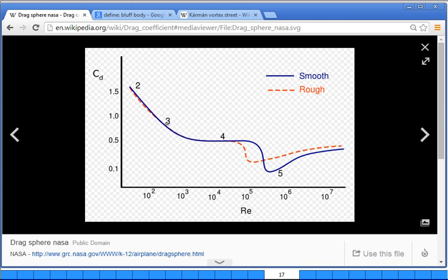But then what happens is you still have laminar flow over it, but it's difficult to recover the pressure to come around the backside. Something happens on the backside. It starts shedding vortices, the little street of vortices being shed. As you increase the speed, it even becomes more difficult. And you develop separation points in the wake region. And then out here, you start to get the very high Reynolds number. What happens is you dip down and then back up. You had laminar flow on the front half coming around that sphere.